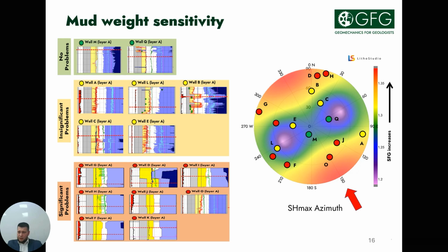Well points in radial coordinates of deviation and azimuth are uploaded on the stereonet on the right. Sensitivity analysis is carried out until the behavior on the stereonet corresponds to the actual points. Points are highlighted in different colors depending on intensity of collapse. The red are strong collapse, yellow and green moderate and minor collapse.